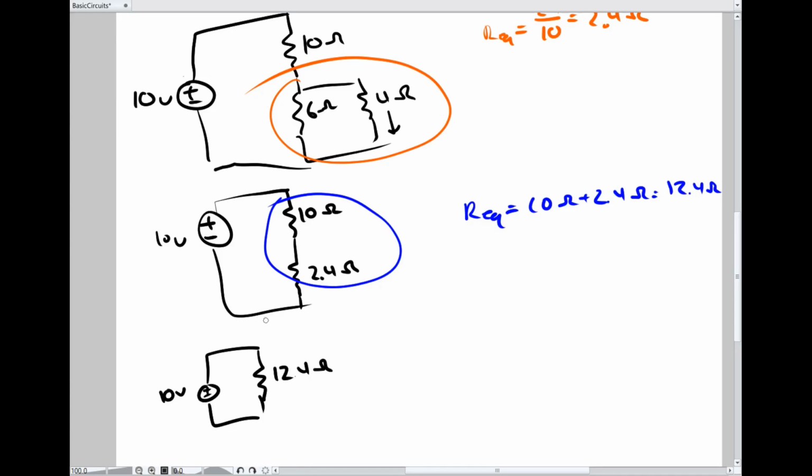Then we apply Ohm's law to figure out what this current is. And here we're going to encounter something important called passive convention. We'll touch on that later. So we apply Ohm's law, and that's just 100 over 124 amps, which is equal to 25 over 31 amps.